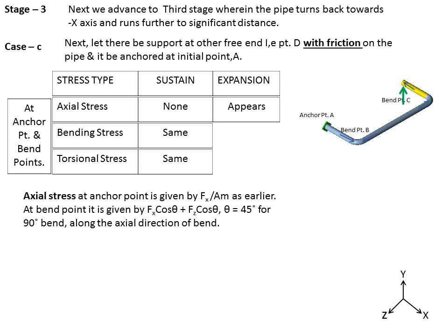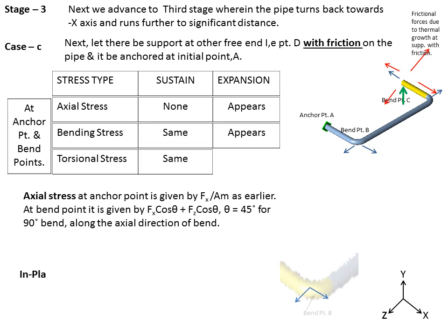So herein what's going to happen is that axial stresses in this animation, because the pipe is trying to grow thermally and there is a friction which is restricting the movement of the pipe, we have the stresses generated, axial as well as the bending. Bending stresses also appear.